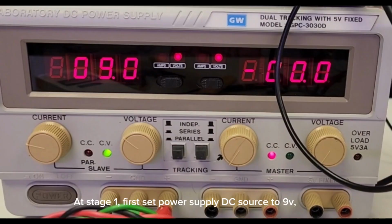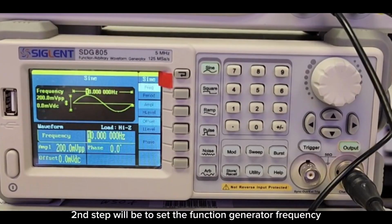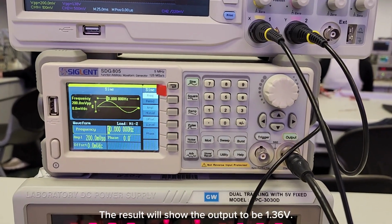At stage 1, first set the power supply DC source to 9 volts, and then connect the clips on the power supply to the circuit. Do not connect the green clip. Second step will be to set the function generator frequency to sine wave at 10 Hz, 200 mV peak to peak. The result will show the output to be 1.36 volts.